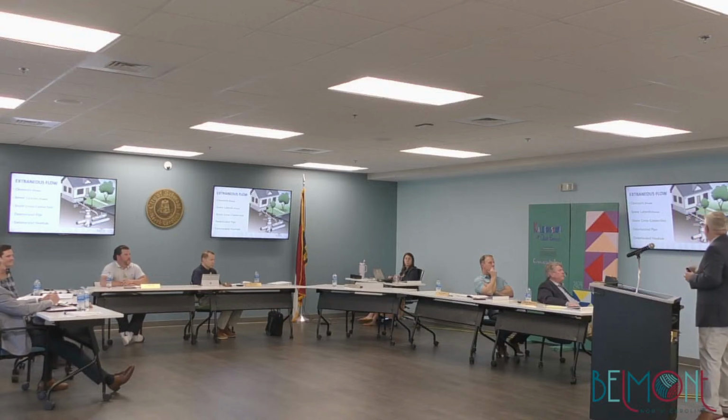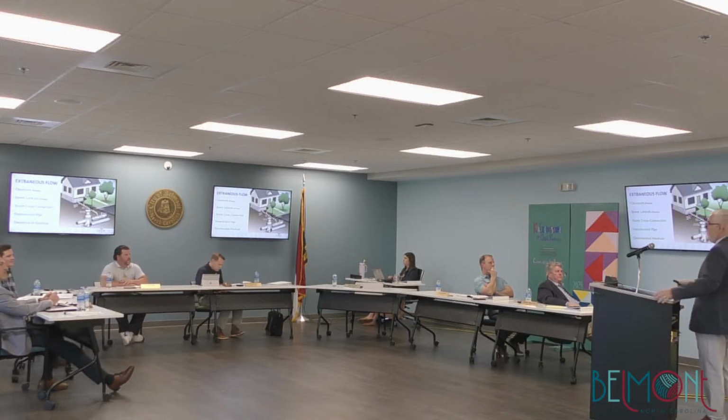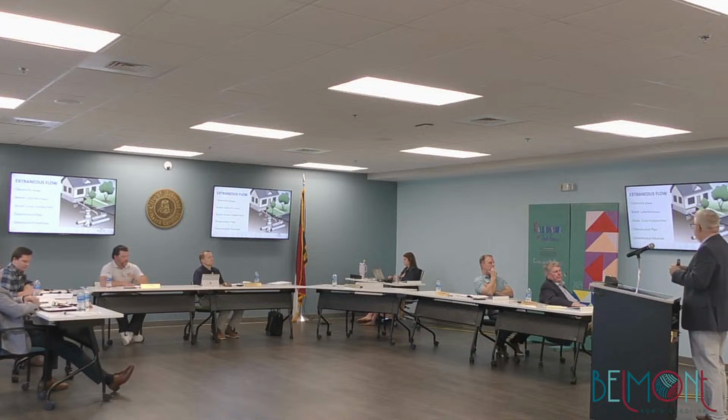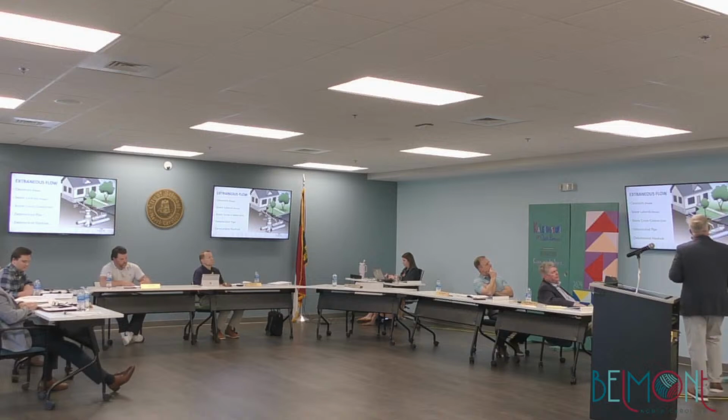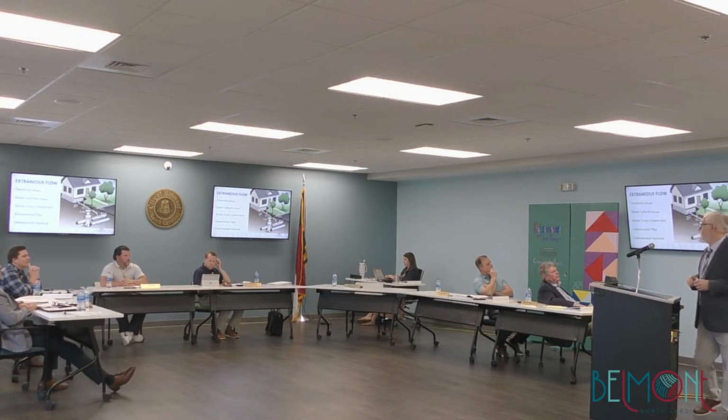If their gutter is connected, they're going to see smoke coming out their gutter system on their house and think the house is on fire. So again, there's a public campaign that needs to happen if you're gonna do that. But smoke testing is really inexpensive. It will identify some of your major contributors. And the fix for that cleanout cap is go to Lowe's Home Improvement, spend $4 on the plastic cleanout cap and put it on there.